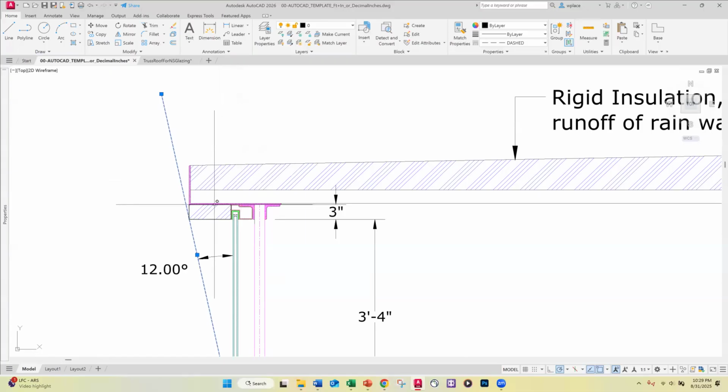So this gets welded to the top. This angle up here gets welded to the top chord of the truss. And in your case, the top chord of your truss will be a tube, so it's pretty good from a torsional point of view. But it's also true that this decking is sticking out sufficiently.